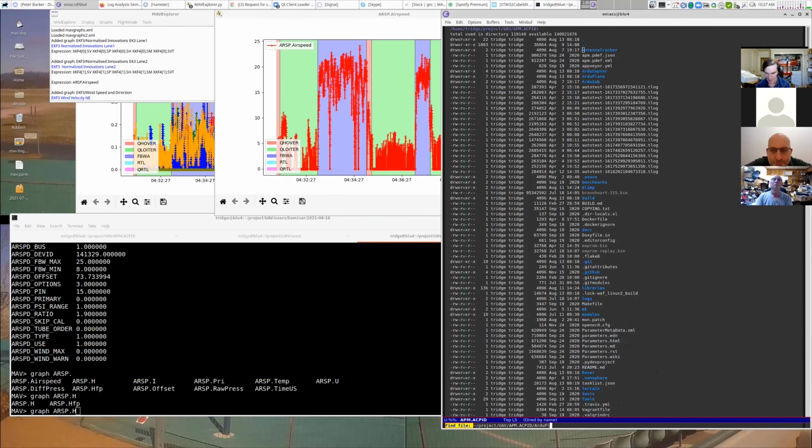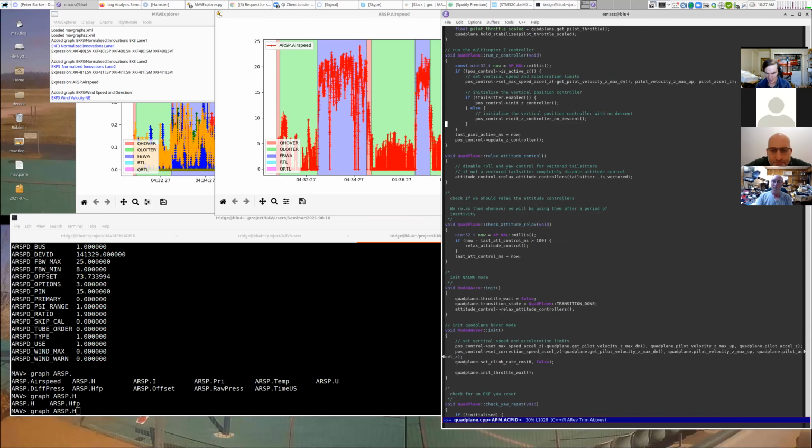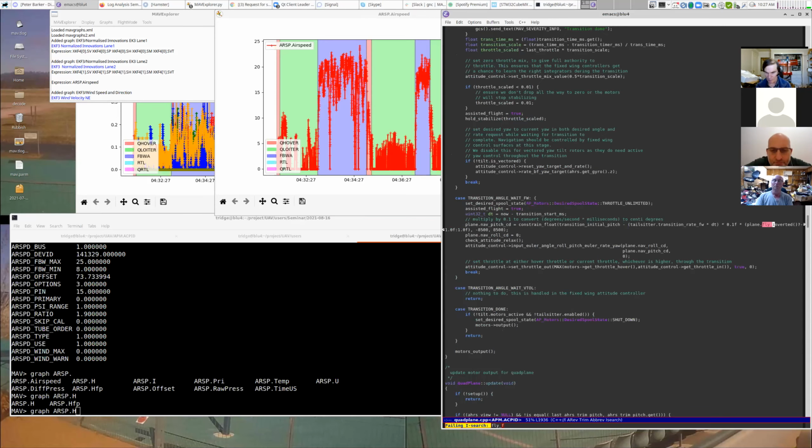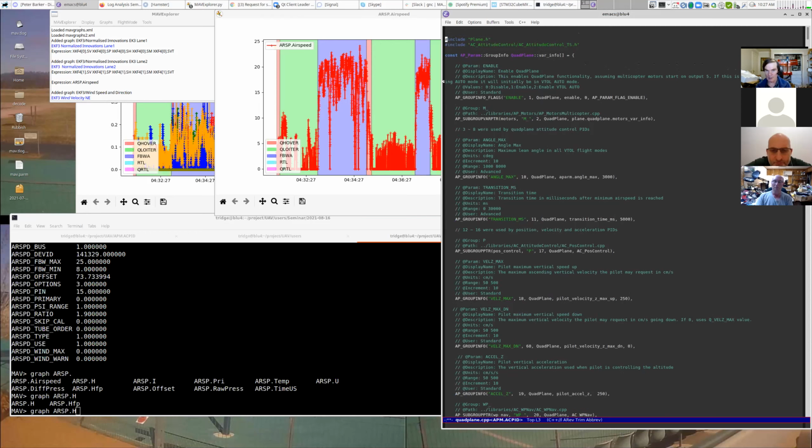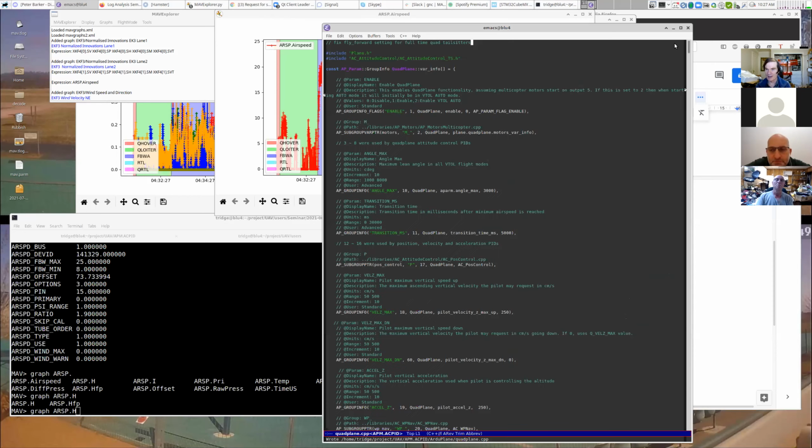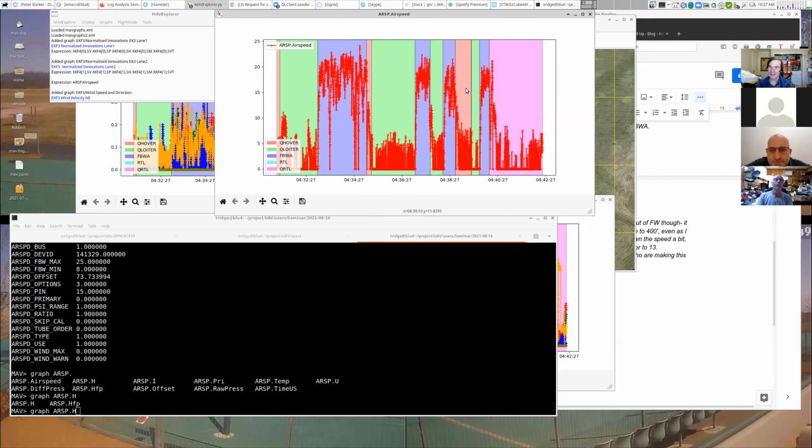So we need to, in ArduPlane, quad plane, fly forward. I'll just put a note to myself: fix fly forward setting for full-time quad tail sitters. All right, little note in the code there that I need to fix. So that's a bug, and that will improve our airspeed estimation.